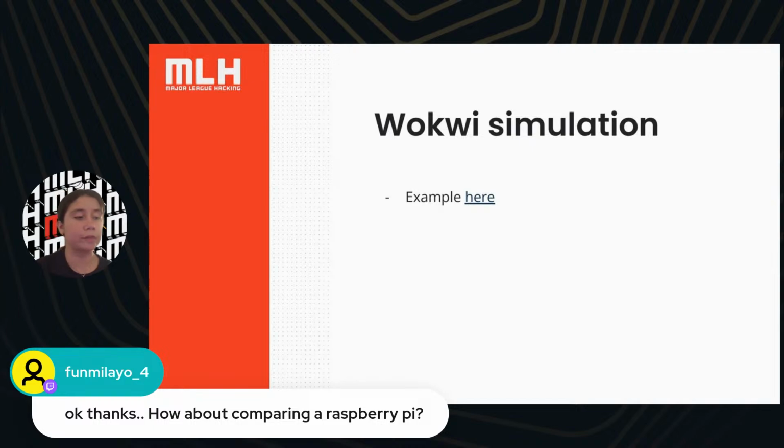So, for example, if you're going to be doing a really complex IoT project, or if you're going to be training a machine learning model or a computer vision model, then it will be nice to have a Raspberry Pi. Also, if you want to get more familiar with Linux and understand the terminal and all of that, you will go with a Raspberry Pi. But if you just want to understand the hardware and controlling peripherals, such as motors, LEDs, sensors, and so on, you want to go for the Arduino.